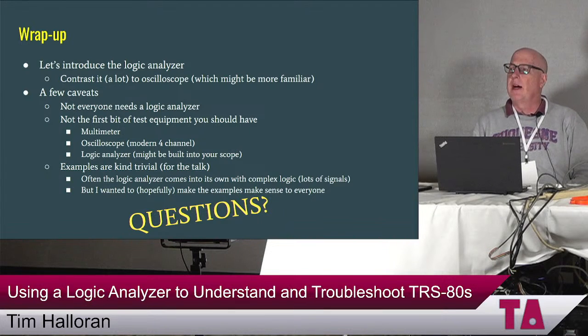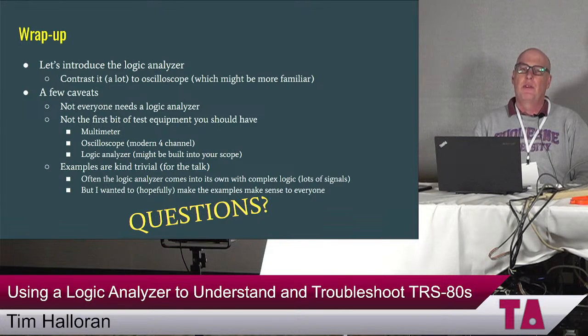Okay, so Lee found the Digital Discovery to be useful. It's not professional grade by any means, and definitely not protected, but probably fine for poking around at 5-volt TTL kind of stuff. And that was more around $150, so that's worth checking out. There are lots of things. Like I said, not everybody needs one of these, but if you're trying to figure out how to add something to the bus and you can't figure out what the bus is doing, this is probably the tool you're looking for.